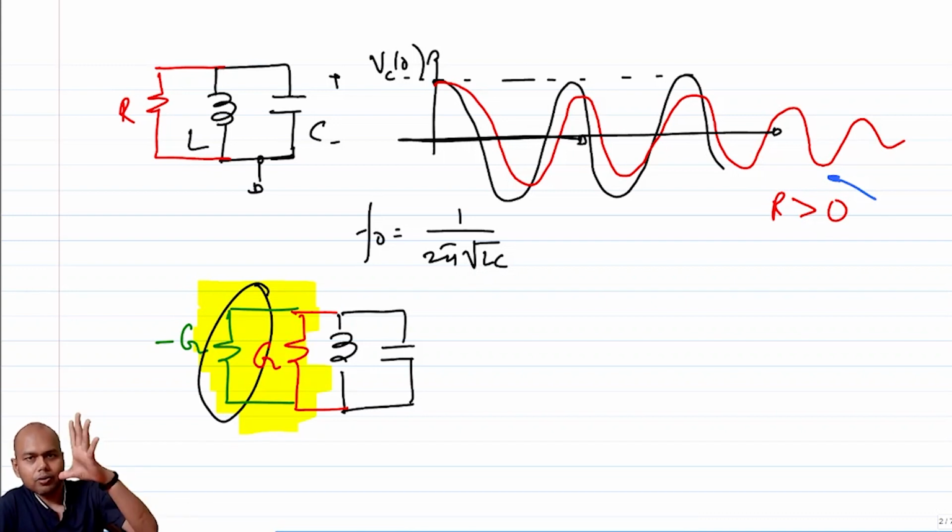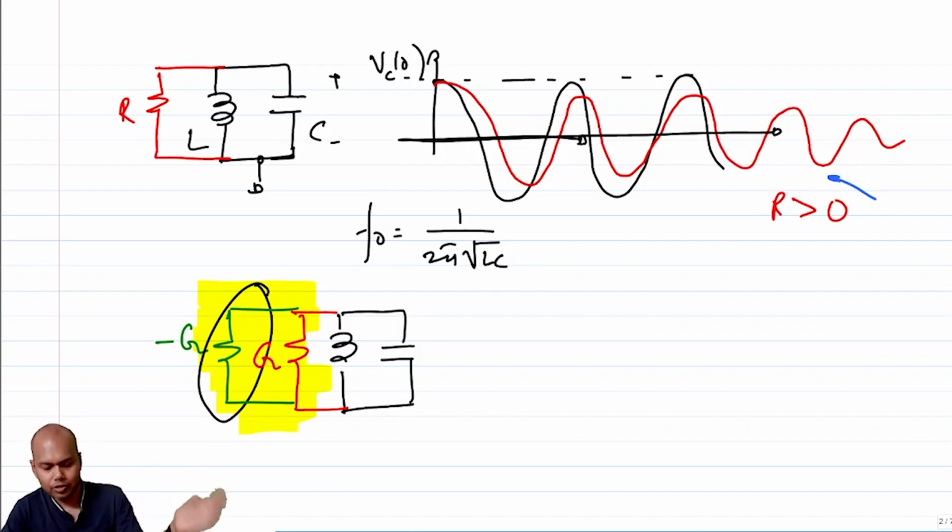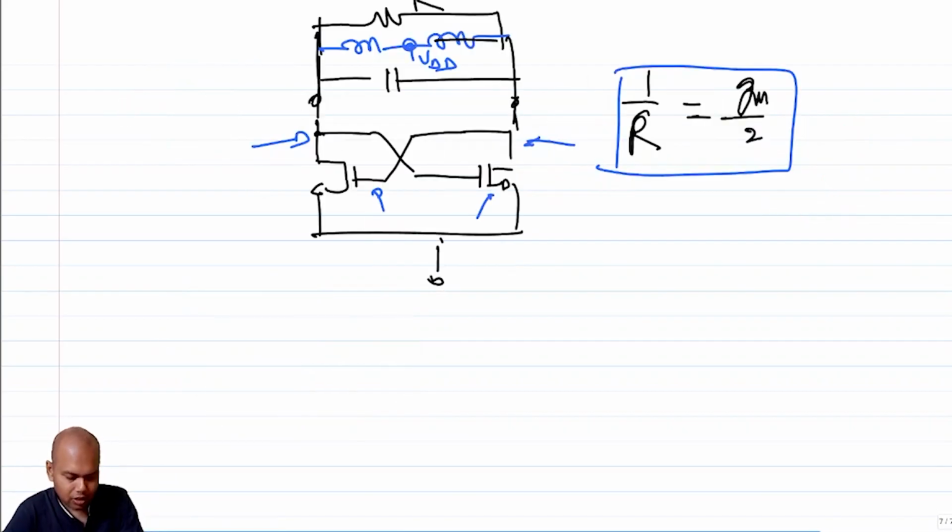The oscillations are going to expand. The amplitude is going to go up and it will eventually go to infinity, right? I mean, you can work it out. You can find out the effective impedance of this network with taking R into account. And when R is negative, find out the location of the poles. You are going to see that the location of the poles will go to the right hand side, and eventually everything is going to blow off, correct?